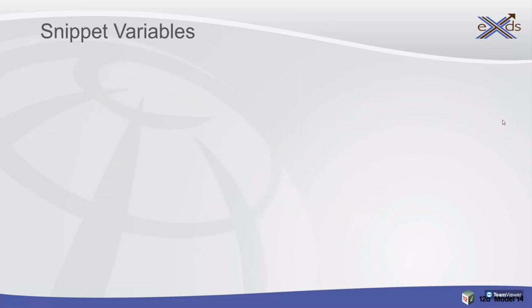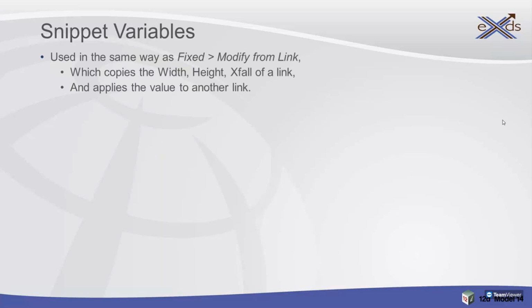Snippet variables. So we're getting into a bit more heavier stuff. I think one comment Tony asked was, what's the difference between a variable and a parameter? Parameters are basically fairly static. The user sets a parameter or you use an auto parameter. When you hit recalc on the MTF, those parameters are set and they maintain that value for the whole recalc.